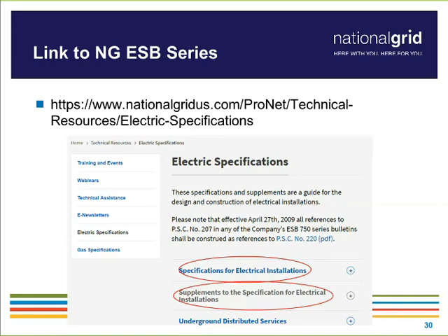Then we get into, again, the field verification where the engineer goes out, takes a look at everything, compares it to the construction drawings, make sure it all matches. Then we get into the witness test, final verification, go through all the test plans, the sequence of operations, so on and so forth. And from there, if everything is successful, we'll go to the permission to operate. So again, a lot covered in a short amount of time, but everything can be found within our bulletins and also discussed during our construction calls.